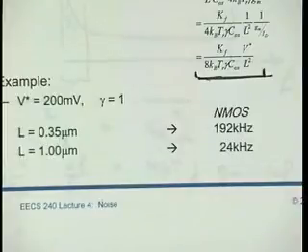One of the biggest problems with flicker noise, I may have said that already, is that often it's just not characterized. Often it's difficult for you to get good characterization data. So flicker noise is really a big issue. You build this wonderful 20-bit oversampled front end with an A to D converter and so on, then in this 1 kilohertz bandwidth, flicker noise is all the noise you get. In that case, you may have to fabricate devices and extract flicker noise for them yourselves.